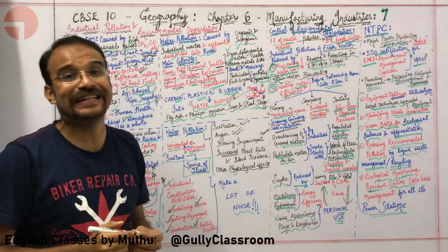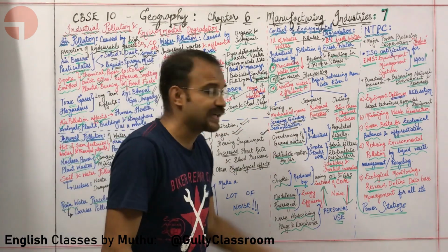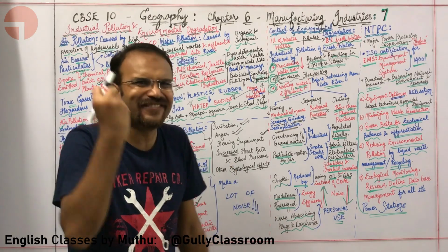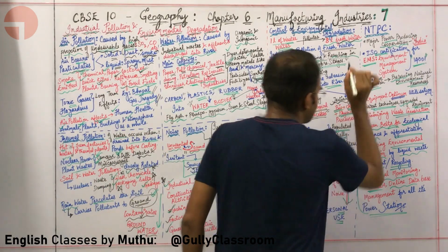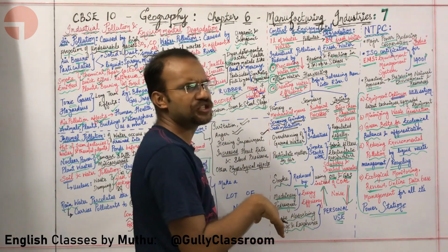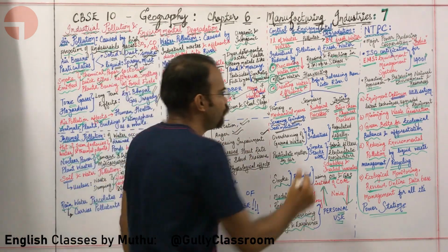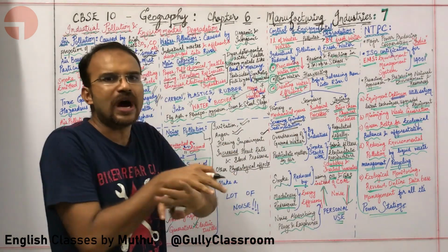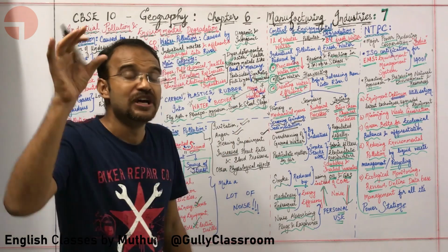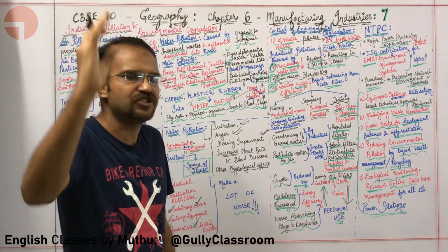There are certain bacteria that can eat chemicals. In the secondary step, we will add these bacteria and use them to eat away the wastes. What about the last step, which is the tertiary step? In the tertiary step, we will use a combination of biological steps, chemical steps and physical processes to ultimately clean the water. So these are the three steps by which you are going to control the amount of water pollution that is done by the manufacturing industries.